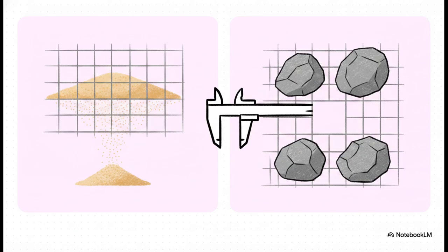Fine aggregate is officially classified as being strictly smaller than 4.76 millimeters. Conversely, coarse aggregate is greater than or equal to 4.76 millimeters. That tiny, specific measurement, which actually corresponds to the size of an ASTM number 4 sieve, is the universal magic line between a tiny grain of sand and a structural piece of rock.